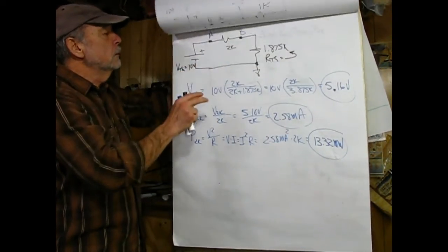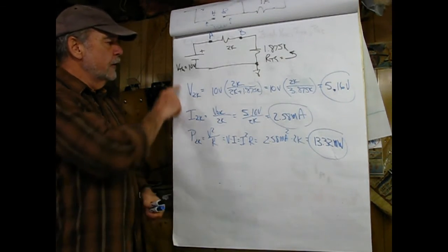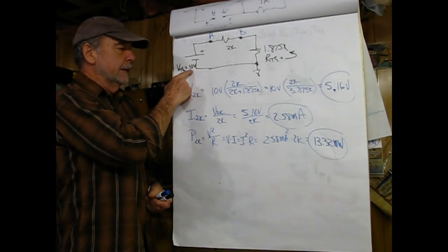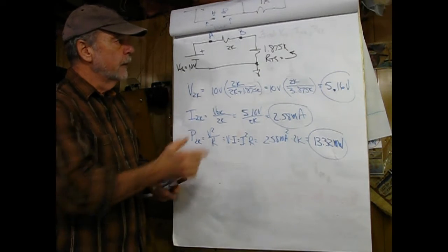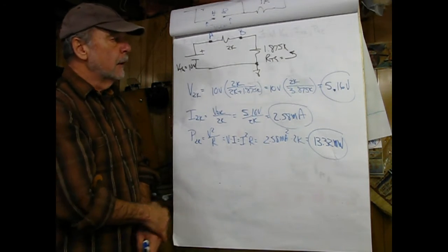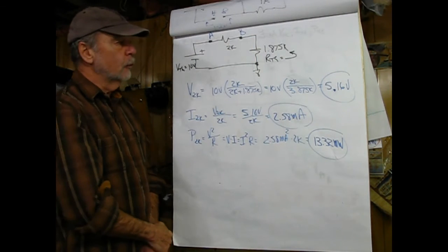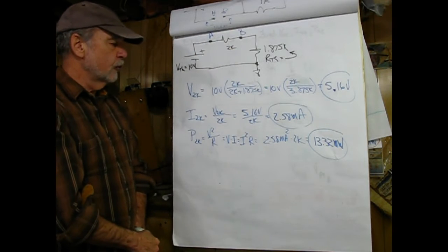So, here's our circuit redrawn. VTH equals 10 volts. And usually it's going to be less than this, but in this particular example it's 10 volts, and it's one of the reasons why I did that. We're replacing our combination of three resistors with our Thevenin, which is our 1.875. Circuit topology remains the same.